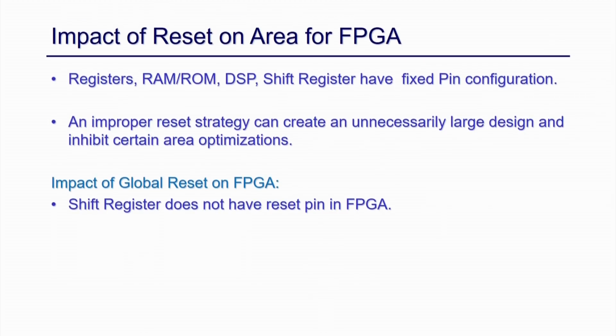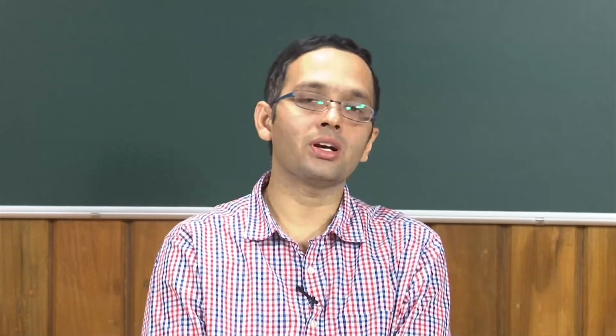So, if you try to map your design to an FPGA, it is very important to understand the exact pin configuration of the FPGA block, because sometimes you design something without understanding the exact structure, and because of only a synchronous or asynchronous reset pin, that whole big RAM or DSP cannot be mapped to the target architecture, right.